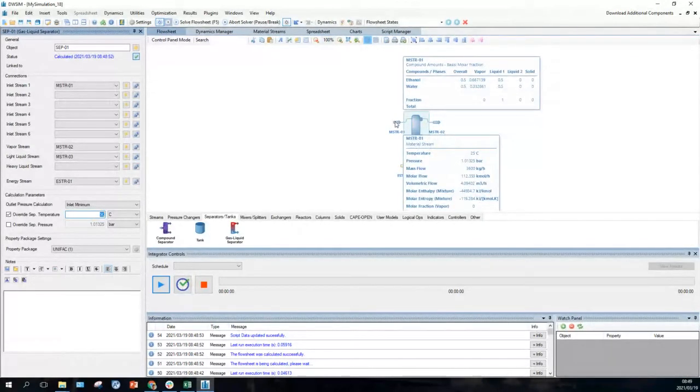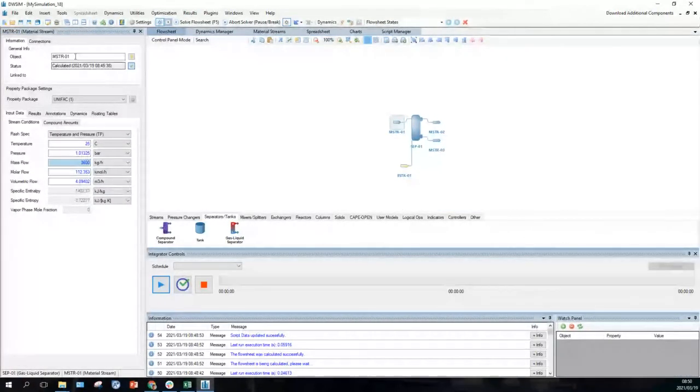So if you look down, I can't show it now, but if you look down at the bottom box, it says 3,600 kilograms per hour. And the mole fraction of vapor is 0, which is understandable, especially if you've got half ethanol, half water at 25 degrees C. Okay, so now we're going to start changing this thing. So I'm going to click it. As soon as we click this, we'll see the left-hand side, which used to be SEP01, is going to change to the stream. This is M stream number 1, and this is what we've got in it.